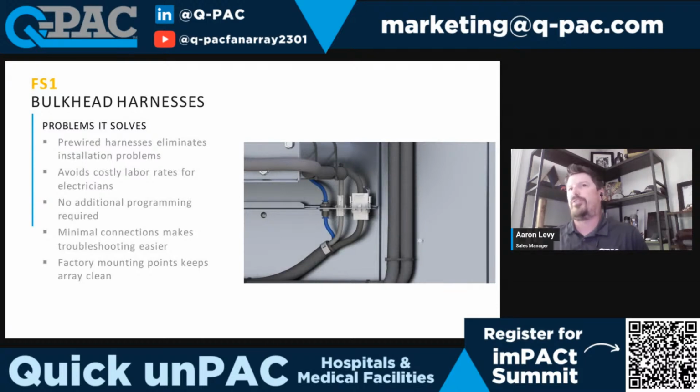Yeah, so that's fan efficiency grade and fan efficiency index. I can touch on it really quickly because it's not too bad. It's to compare AC motors to ECs to give them a more apples to apples playing field. The main problem is that EC and AC fans don't have the same power factors, so that's why sometimes we use FEI and FEG to make them even. We do have an FEI calculator in our selection software. We have the ability to send that out, and we can give you what those numbers would be if requested.